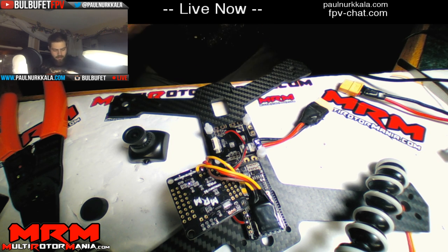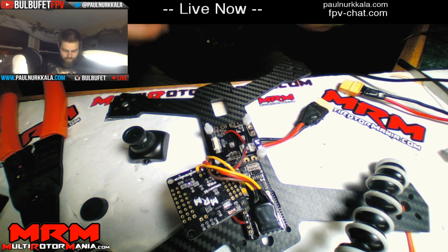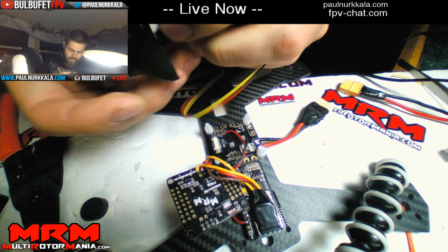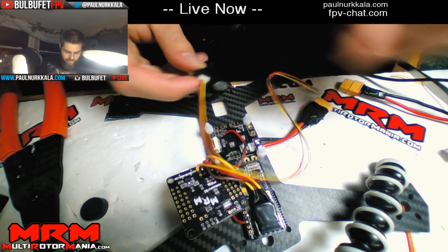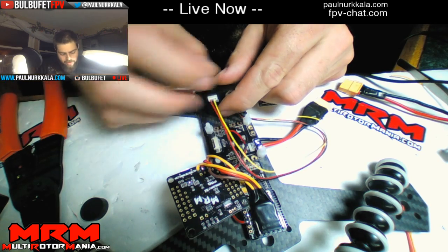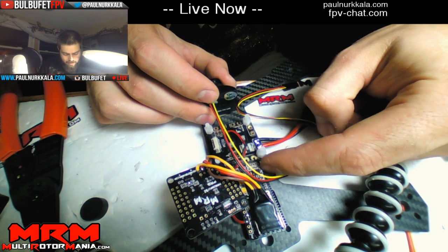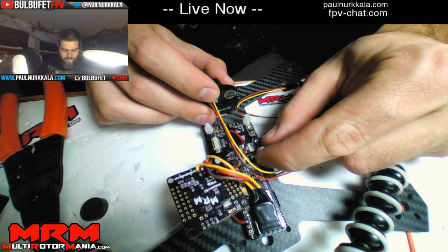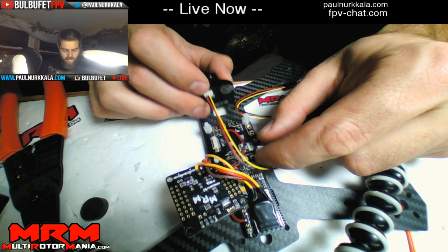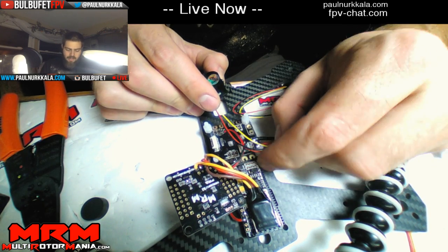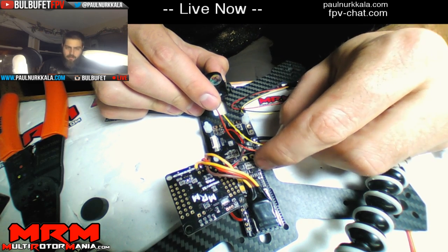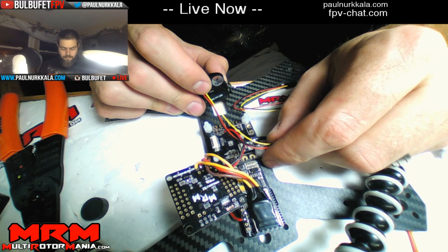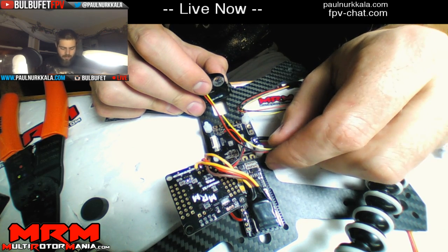Okay. So this wire does three things. It connects to the camera here. So we've got, this one goes like this. So we're going to power the camera off of these 5 volts, and then we've got to run the cable back to these ports back here, the video cable, because that is going to be the video in from the OSD. And that's going to take the signal from the camera, convert it, add the OSD, and then send it back out to the VTX.